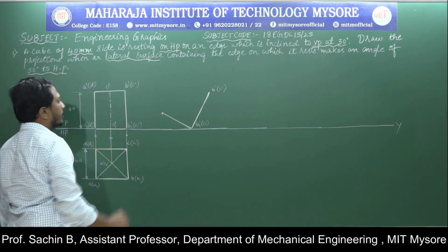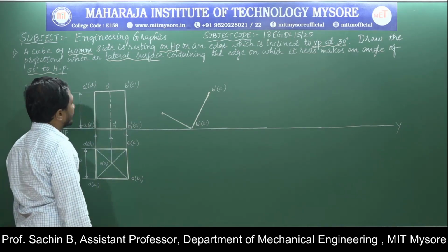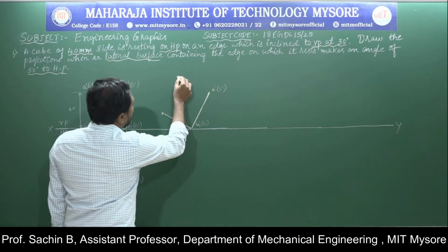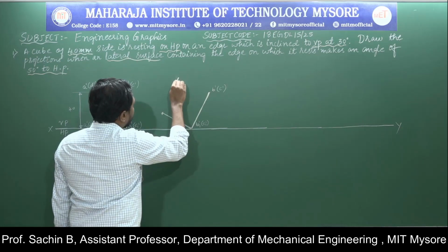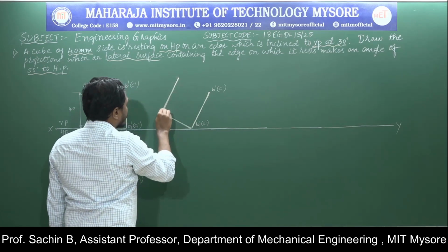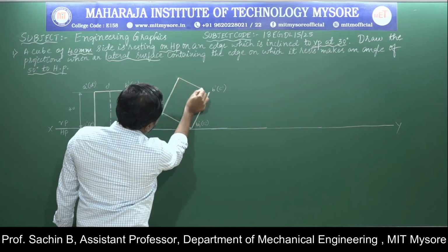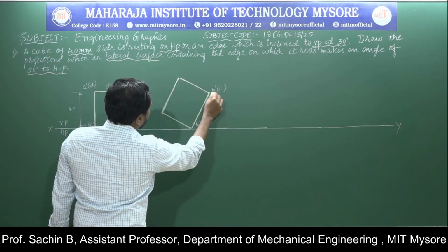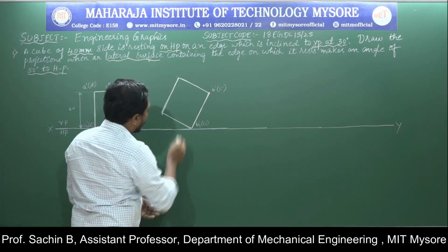Okay, now to get the remaining point, that is nothing but the A dash point, I will measure from A1 dash to A dash and put an arc here. Again I will measure from B dash to A dash, one more arc towards this side. Now I will join this. Now I will measure from B1 dash to O1 dash to get the midpoint.